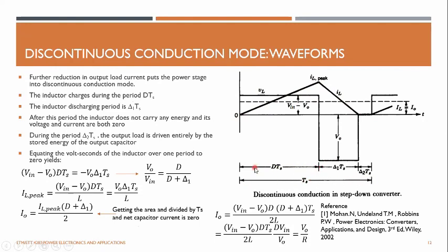And this is the turn on time, DTS. We have two terms: delta 1 TS, the period where the inductor current goes to zero, and delta 2 TS, which is this dead time. So basically, the controller turned on the switch, and this total period is the turn off period, and it has two components. One component where the inductor current goes to zero, and another for this dead time.